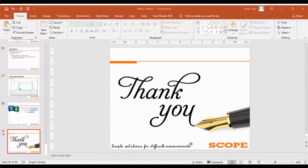One more question I can see is about dry and wet contacts. It's about the auxiliary contact. We can measure the timings of the dry contact and the wet contact. A dry contact is a potential-free contact, and a wet contact is a contact with potential. We can measure the timing of both, and in our equipment we also have a facility to configure the dry channel for wet channels.